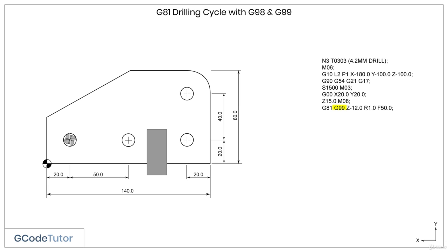So why add a G99 in the first place? Well, this gives us the option to also add a G98 line within the program, so we can hop over clamps. Let's read through the program so we can see how that works. Dimensionally, it does work the same as the G81, as we've just done. An X50 incremental move takes us to the second hole and automatically drills it.